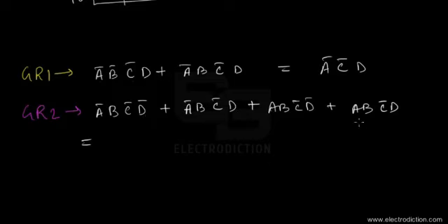We can see here that only the term B C bar appears constantly common in all of the 4 terms. So upon reducing this entire thing using De Morgan's theorems and the basic laws of Boolean algebra, we get this term B C bar. Now for the third group over here, that's the green quad, group number 3.